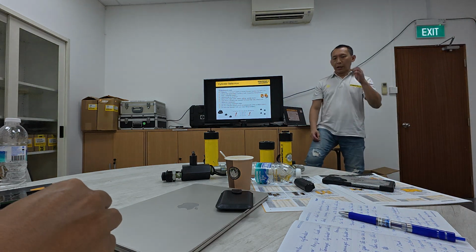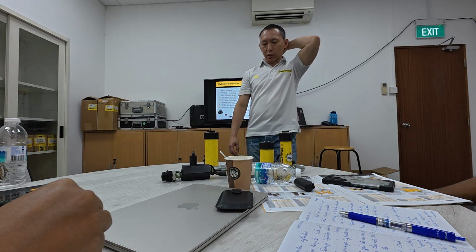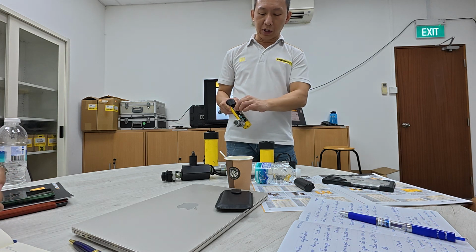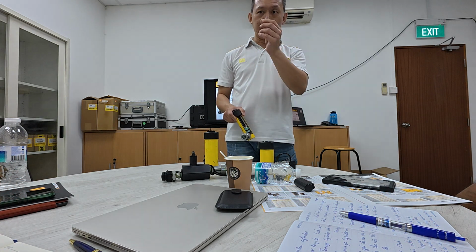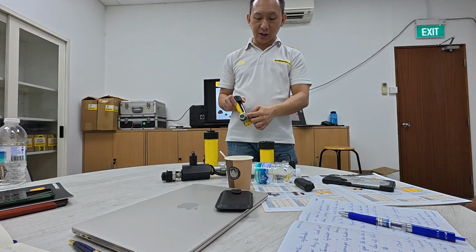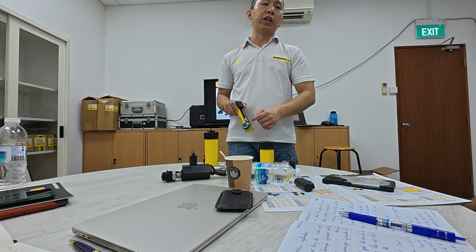Okay. Push out with the 700 bar. So what happens is, if let's say for example, side load doesn't mean straight away leak. Because if there is a side load at the side of the wall, it will scratch, usually leave a mark there, and create a sharp point. So when the cylinder extends and retracts, it will cut the seal. That's why it will leak.